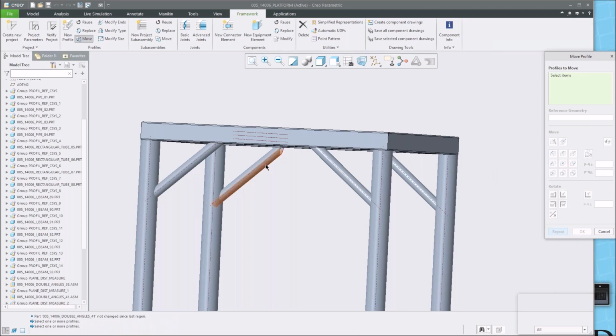Repeat that on here. So when you're copying it or reusing it, it is important to pay attention to the arrow directions, especially if you're rotating it like I did there. I didn't have an issue with this one because they're all on the same side, but I moved that one around 180 degrees, which changed where its profile was.